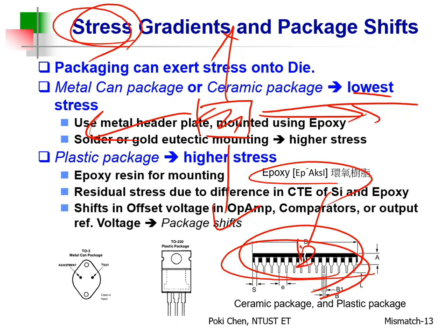So it means what? Your post simulation here, your measurement, real measurement there, right? But this is only for bell die. After bonding and packaging, it will be pushed further from your post simulation. That is what I would like to warn you. Okay? Our lives are so difficult.